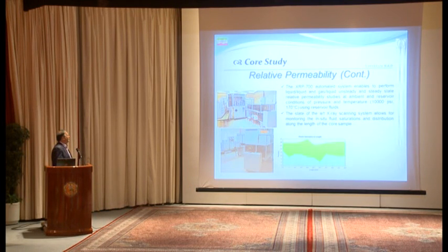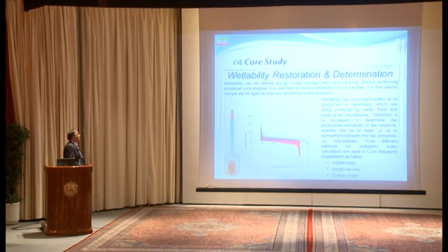The difficulty of measuring relative permeability in the steady state method, as you know, is monitoring of saturation along the core sample. With this X-ray system, we are able to measure saturation along the core sample during gas injection and water injection. And also with this system, we are able to measure three-phase relative permeability. Another technique for wettability measurement is the Amott method, and also restoration of the core sample.